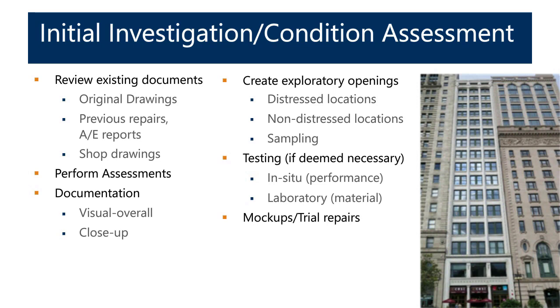Looking at the building either from grade for some of them. Facade ordinances a lot of times are just performed from grade with binoculars. Or you can get up and do close-up inspections. The number of drops, how much of the building you cover, again, depends upon what the owner wants to know, how much they want to know it, and what the end-all goal of the project is.